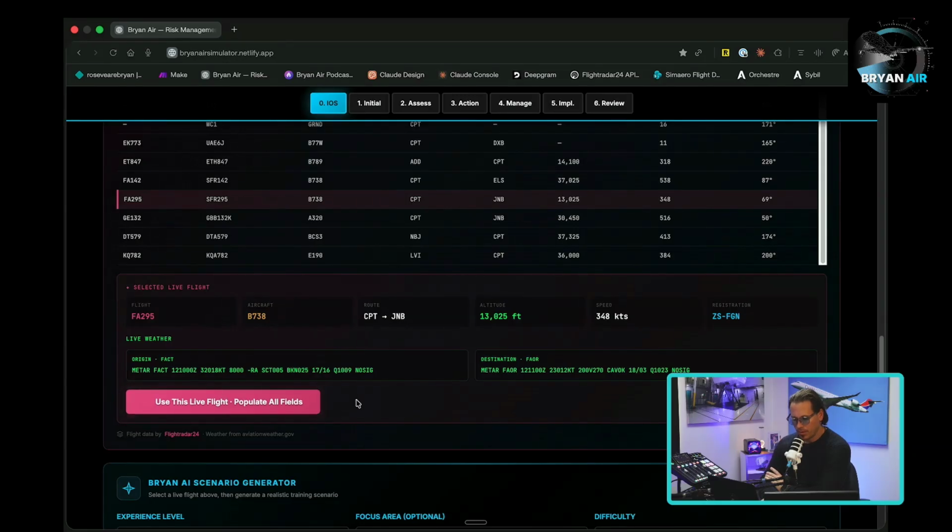8,000 meters, light rain. What's the wind? 32018. It's not too bad. 8,000 light rain, scattered 500, broken 2,500, 17 and 16, 1009. No SIG. OR, it's good here at the moment. I'm actually in OR at the moment. So 23012, CAVOK, 18, 1023.